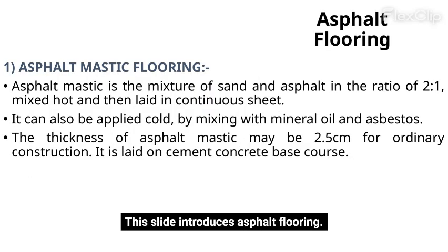This slide introduces asphalt flooring. Asphalt mastic flooring consists of a mixture of sand and asphalt laid in a continuous sheet. It can be applied hot or cold, with mineral oil and asbestos. The thickness is typically 2.5 cm over a cement concrete base.